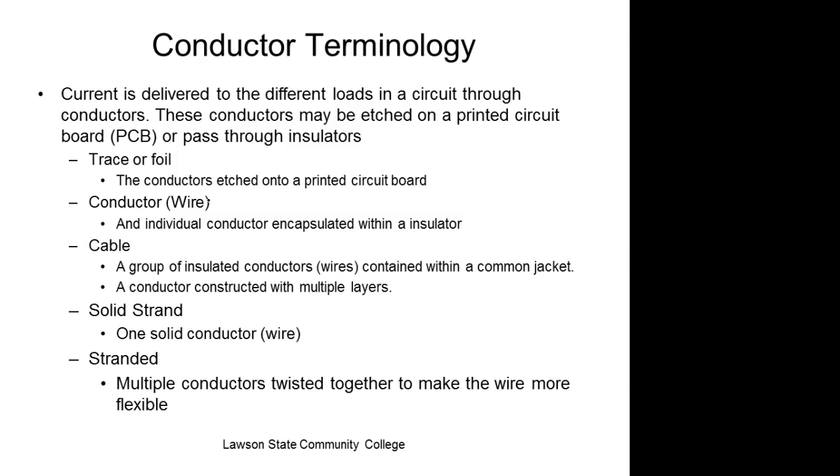I don't know anybody running any house wiring that's solid. Very hard to deal with. That Romex they have, the 14 gauge Romex, it's hard to bend. It's hard to do because it's solid wire. What advantage solid has over stranded is that we can terminate it. We can wrap it around a screw and tighten the screw down. So we can take a piece of solid, put it in a loop, put it on a screw, and wrap it down. We can splice it. We can twist it together. Stranded, we're not supposed to do that. Stranded is supposed to be in something that maintains the strands. Because if you've got one strand that comes out from under that screw, you've changed the gauge of the wire.